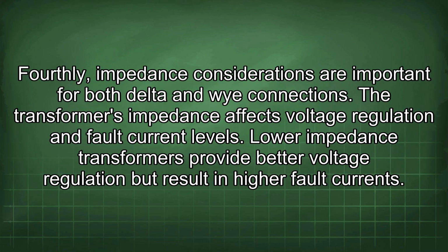Fourthly, impedance considerations are important for both delta and Y connections. The transformer's impedance affects voltage regulation and fault current levels. Lower impedance transformers provide better voltage regulation, but result in higher fault currents.